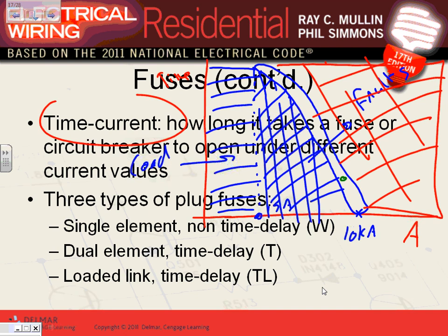So say you have a ground fault, and I'm going to say this is 30 cycles. If you have a ground fault of, say, 7 kilo amp, it takes 30 cycles to clear it. I'm just throwing these numbers in cycles. If the short circuit is higher, right here, it will take 3 cycles. This is what they call the time current characteristic curve. You're going to study this in detail as we move on, so I'm going to stop right there. But that's what they're talking about, the time current characteristic curve, which is that curve right in here. It has a relationship: the higher the amp, the faster that baby will trip.